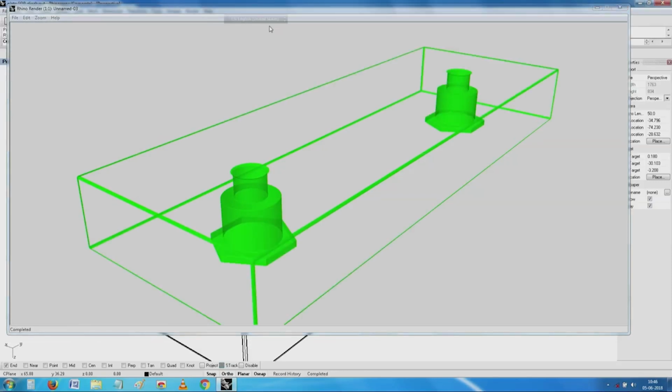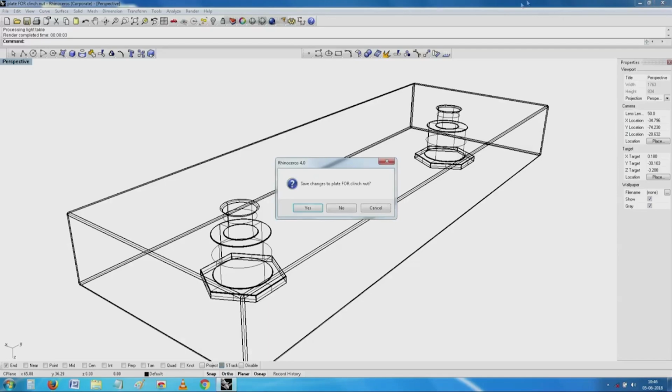Seen this, no? They are the edges of it, and inside we have that small depression which approximates to the nutsert, or the clinch nut, which I am going to push inside. And after putting the clinch nut, I will have a surface which is again, as said, 0.8 or 1 mm polycarbonate, which is generally hard, and depending on whether we have an adhesive which melts and sticks to that. Now, we have a beautiful object which is very functional, plus I can play around, make it into any shape I like, and it is a build, and we can clean it. I just wanted, as part of the fastening mechanism, to show you this.